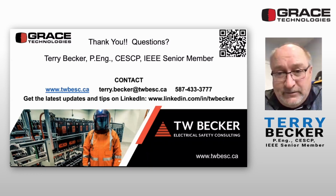I was just on a client site yesterday. They just did a power factor correction capacitor project. They're installing 25 kV capacitors, 4160 and 600, and I advised them the timing of this new information is relative. But again, the manufacturer of electrical equipment cannot label arc flash incident energy analysis data. You have to get an independent study completed and field-based labels installed.